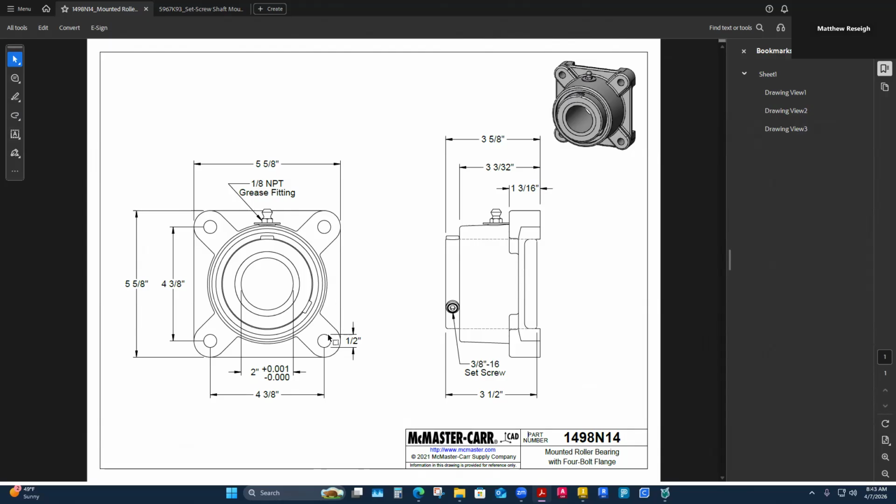We just need something that will clear through here. The fastener that I'm going to thread in my end plate is just going to pass through here. It's not going to thread into these; they are a through hole. They just slip over a bolted connection or a bolt or some kind of fastener. So I just need to have a fastener that's undersized to half inch and is still readily available. 7/16 made the most sense to me.